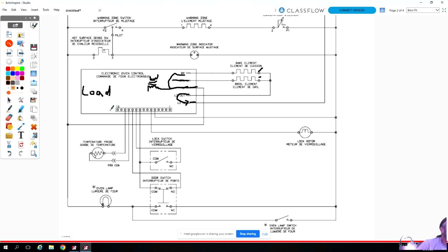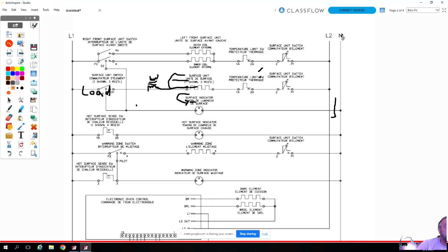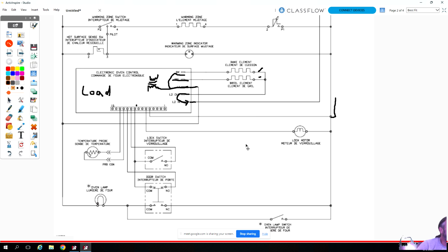Very good. So if you look at this connector here, neutral's this wire here. If I bring the diagram down, I'll show you. Neutral's that outside wire here. I'm going to bring this back up. So neutral comes in here and runs into pin 5 on the control board.